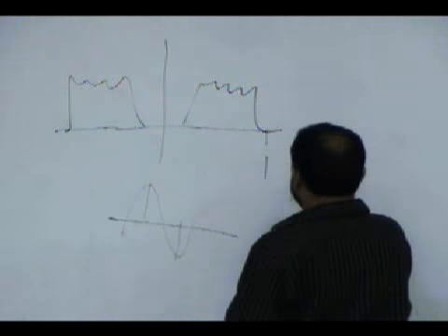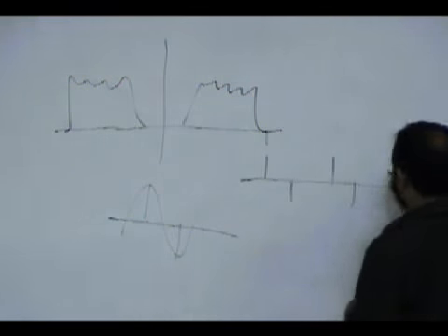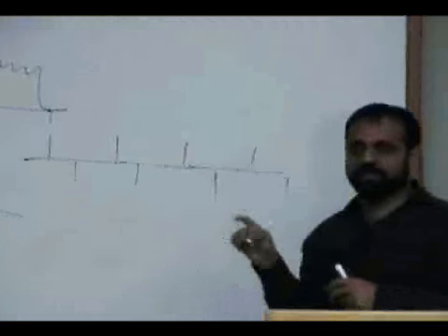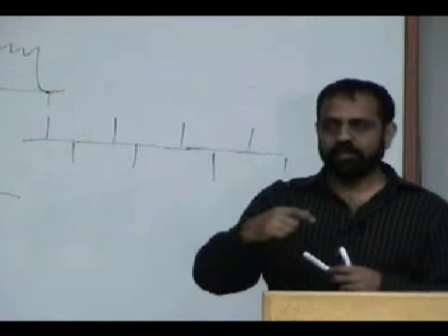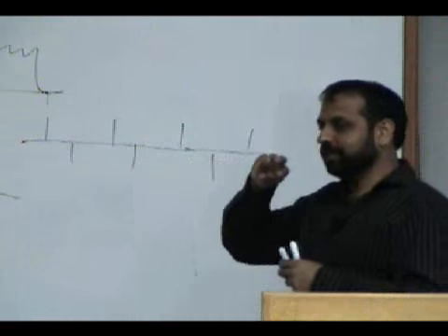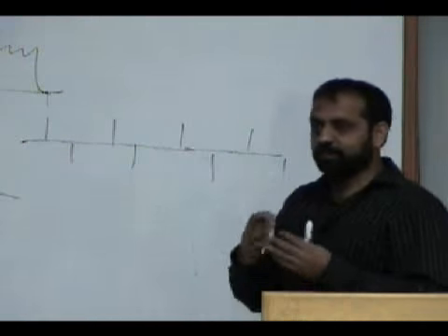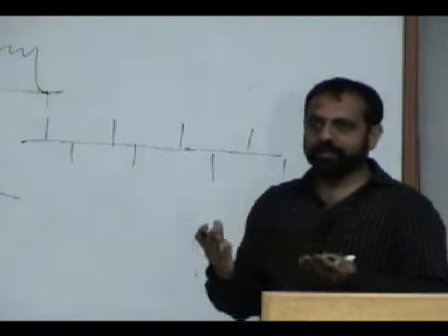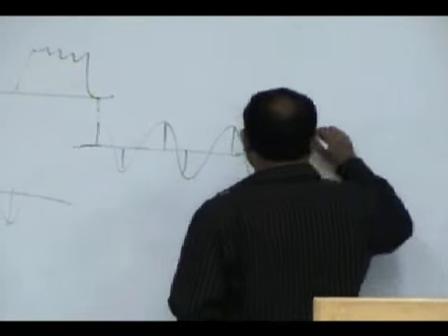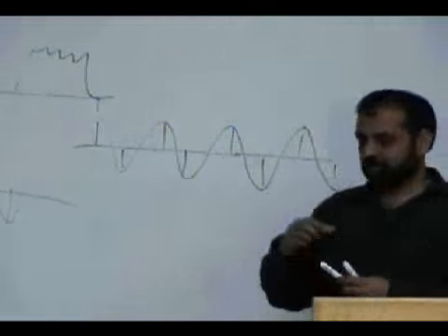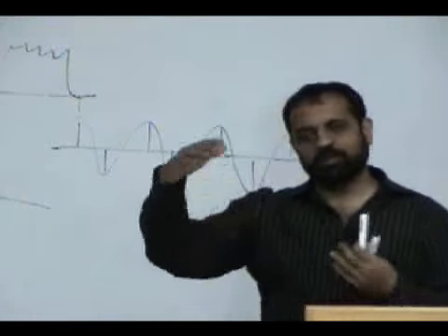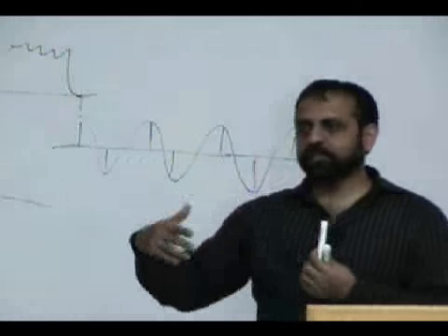This is very interesting. If you put this signal, and actually we have done this, to a D to A converter, it will generate a sinusoid. So the magic in a D to A converter is that it can interpolate and generate a frequency. You put this in, it will exactly generate this, because it has a sample and hold, and then going through a smoother or a low pass filter will generate a cosine for you.